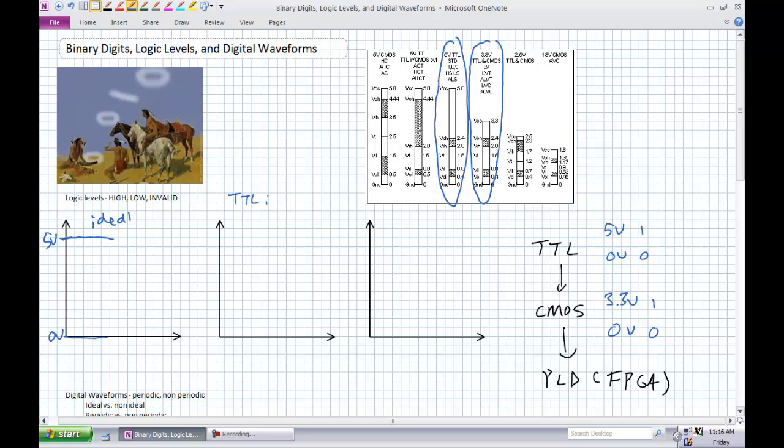For the TTL range, input, since that's the one we're going to use the most, I'm going to go over this one a little bit. What is the acceptable value for a 1? There's this thing called VCC, which is our supply voltage. That's 5 volts, obviously a 1. For an input, an acceptable value goes down to 2 volts. So anything within this region for an input is a high or a 1. Our input low acceptable range, let's use a different color for that, is this range here. Obviously 0 volts is definitely a low. What is our input low? Up to 0.8 volts. So anything within this range is clearly a low or a 0.